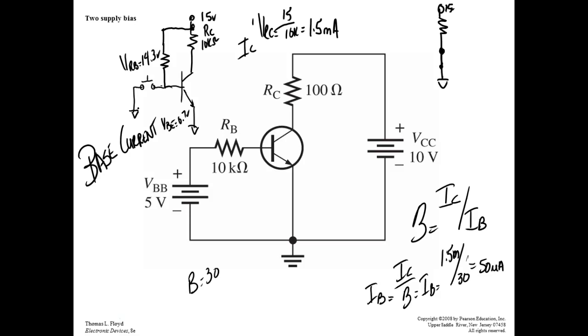So this allows us to control. This could be a digital logic gate. A digital logic gate can source 400 microamps and it can sink 16 milliamps. It can provide a high of up to 400 microamps and a low up to 16 milliamps. So this could definitely be driven by digital logic. A microprocessor would have no problem turning this thing on and off. You understand that? We'll look at it later on and calculate that. What they talked about on the slide was doing this.